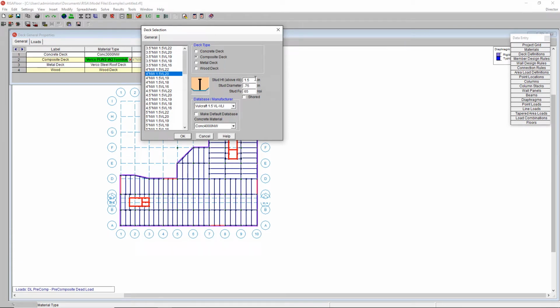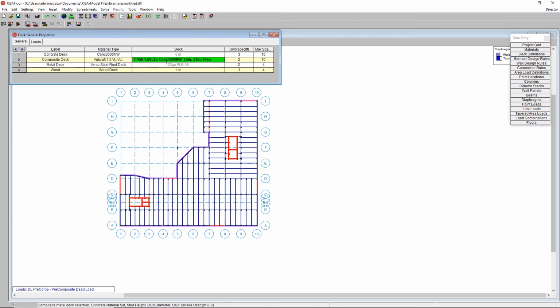So I'm going to say, okay, this is where you define your studs. If it's shored, you define that here too. But I'm going to say this is going to be good for my studs, and I will define that there. This just echoes that back. It just lists out the things that I made assumptions on. The program will use an unbraced length for the top flange of any one of my beams here based on this. This is my 2-foot unbraced length.